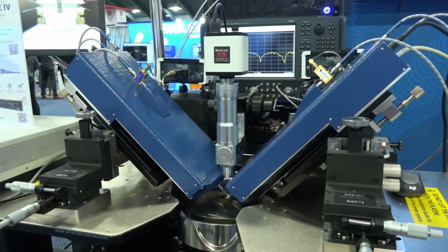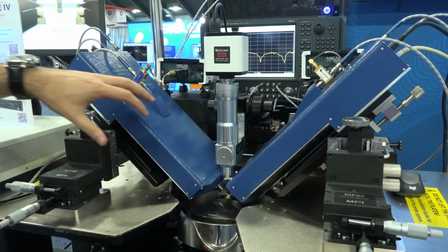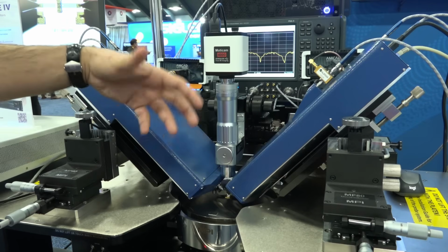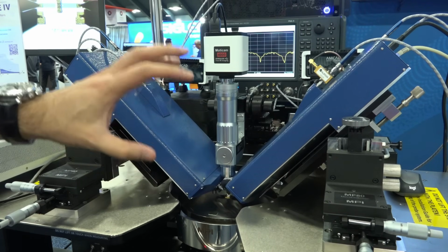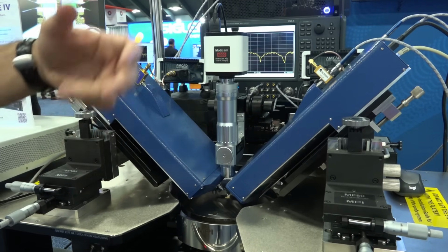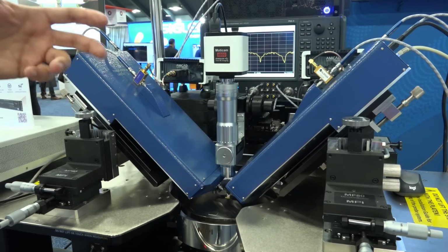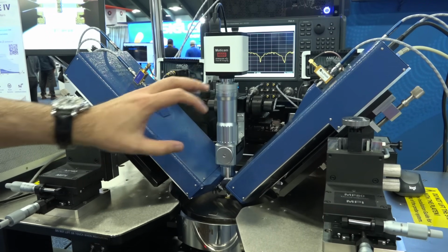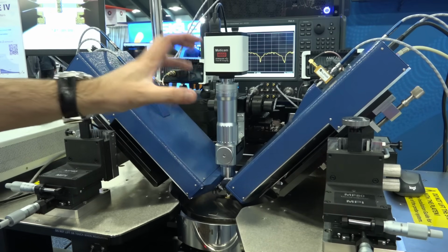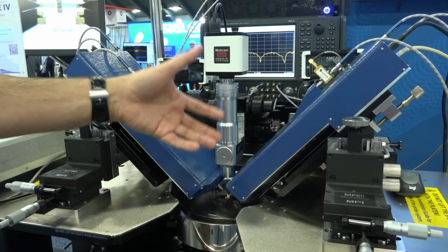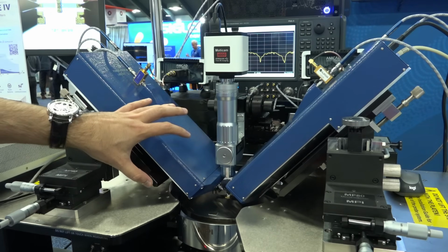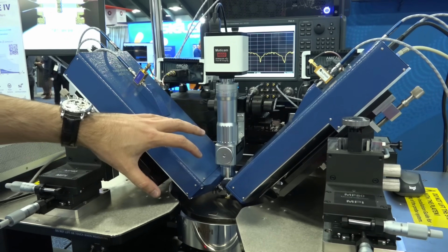So when it comes to load pull device characterization, you have focused microwave heads that allow you to adjust the load pull of a device. You can characterize the device and extract those models for validation. But then on the step afterwards, you can do this new thing that Dassault is doing, which is this RF pulse IV characterization. You basically apply an RF pulse that has the envelope characteristics of the signal you want the device to process under the load conditions you want it to process. And then at that point, you do your IV characteristics.